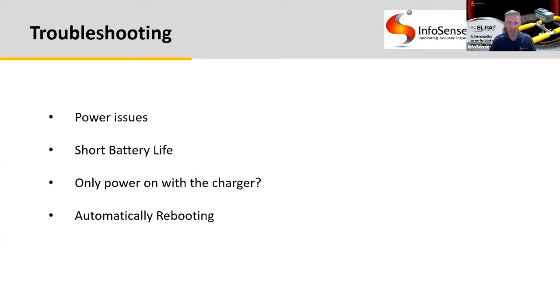If you're noticing the device shutting off on its own or cycling power and automatically turning back on, you probably have an intermittent power circuit inside the device. This could be a range of things, from a loose wire to an intermittent circuit board failure or a damaged battery intercell connection. In this case, the unit will need to come in for inspection to be sure no further damage resulted from the flickering power.